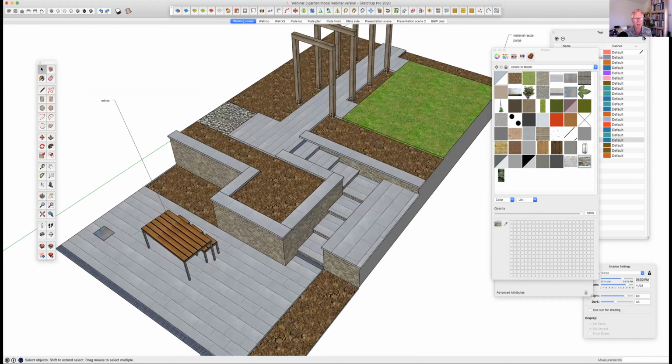So I'm going to go to my extensions and purge. SketchUp has a native purge. I've just found that some of the purges that are applications work a little bit better, and there are several of them. This one is by a guy called Tig, T-I-G, and he writes quite a lot of these technical little plugins, and I think all of his plugins are free.